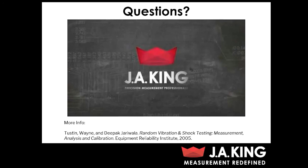Are there any other filters other than daylight and window filters? Yes, so daylight and window glass filters are definitely going to be the most common that you run into, but there are some different filters if your specifications require that. So one of probably the third most common is an extended UV filter, and that's actually going to include a portion of that UVC part of the spectrum. And the reason that's usually used is to help accelerate degradation of parts.